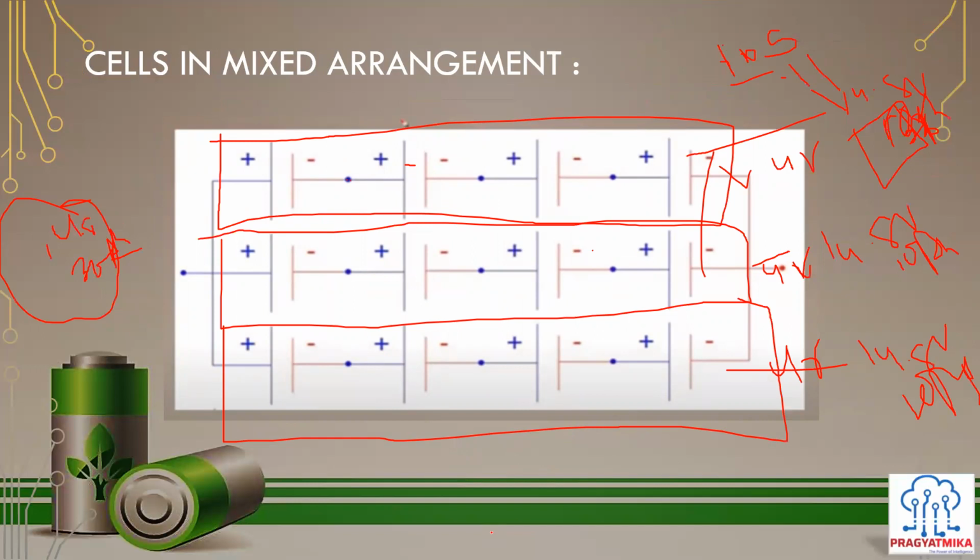But once we are doing the series-oriented mixed arrangement, specifically for applications like EV or solar, the number of cells becomes large. That is why the general BMS is not able to handle them, and there the master slave BMS is required. So if we are using a ready-made 10S BMS, then we would have to make 10 modules of 3 cells in parallel each. That is the restriction which comes on the battery design.